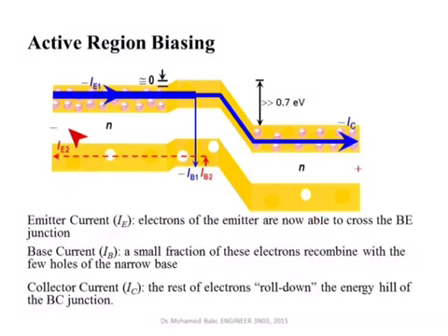So now the conduction electrons in the emitter side will have more energy. They can now flow very easily into the base, and also holes in the base can flow in the valence band through to the N-type material. So you get electron current flowing this way.